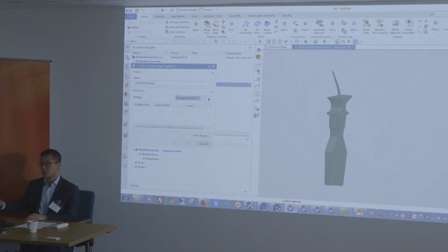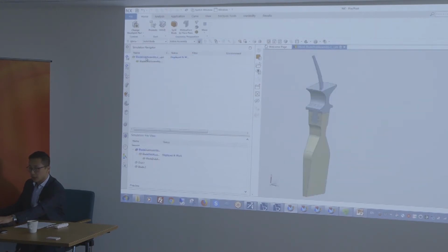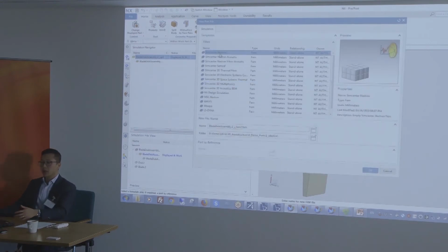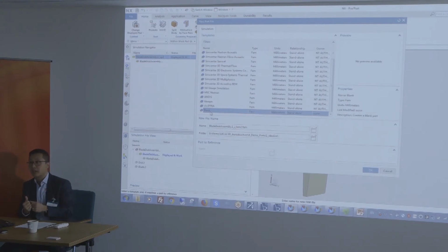Okay, so when we created our, let's say, let me just go back to the part here real quick. When I create a new FEM, these guys, like Nastran, are essentially templates. But I could have a template called Rolls-Royce template, or a blank template that you customized up front, and that already includes all the different selection recipes, all the different meshes that you've created that point to those recipes, so that when you open it with a particular CAD, everything gets meshed on the fly.